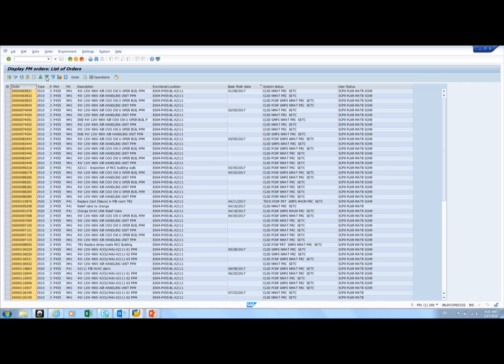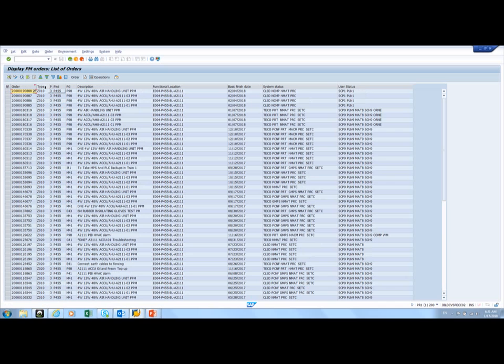By sorting it on the work order and putting the biggest at the top, you'll see the most recent. So that was the last PM that was carried out, and if you saw that it was only completed 2 days ago and now we're reporting a fault, you might question the quality of that PM, whether it was carried out correctly or whether or not it is complete in its requirements. So you might review that PPM and find out why we didn't see this defect then.